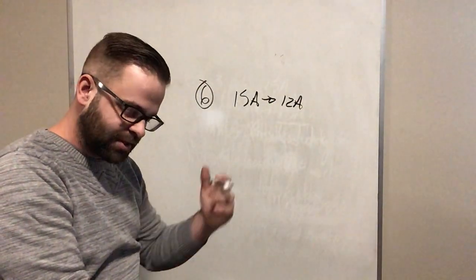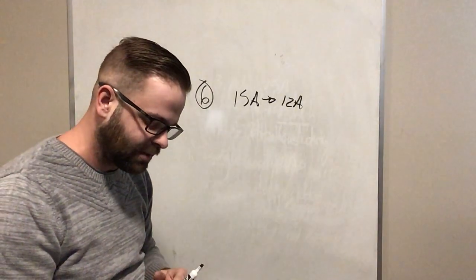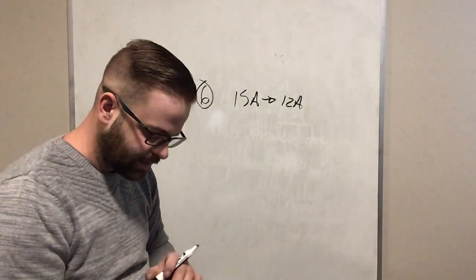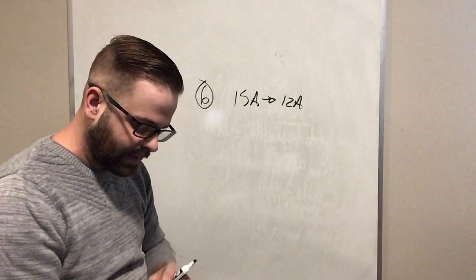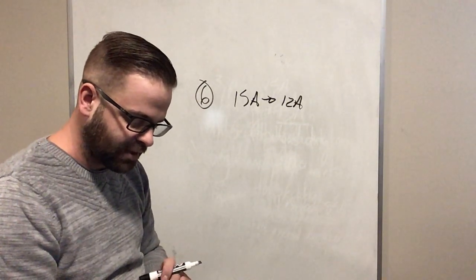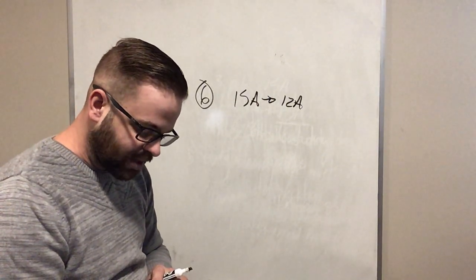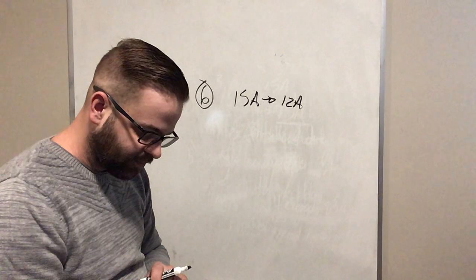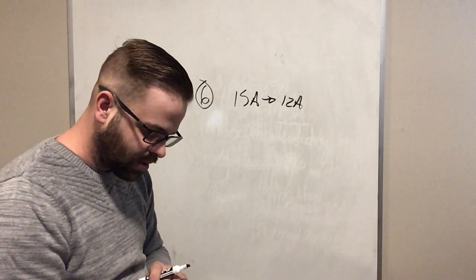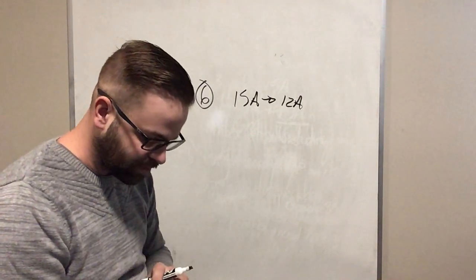So the first instance is an instance where we would barely ever see, where we see a fuse or breaker rated for 100% of its rating. And here is the most common, where that breaker or fuse is rated for 80%. So operation at 80% of the ampere rating of its overcurrent device. The continuous load as determined from the calculated load shall not exceed the continuous operation marking on the fuse switch.